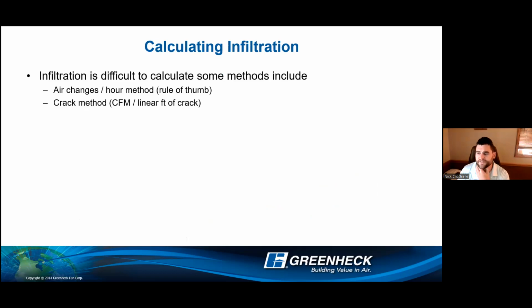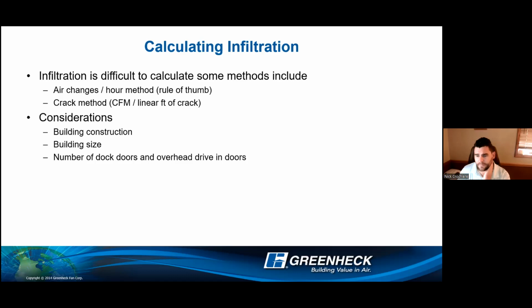Calculating infiltration. So infiltration is difficult to calculate. Some methods include air changes per hour method, rule of thumb, the crack method, CFM per linear foot. Considerations: the big thing is building construction, building size, number of doors, overhead drive-in doors. So the big thing